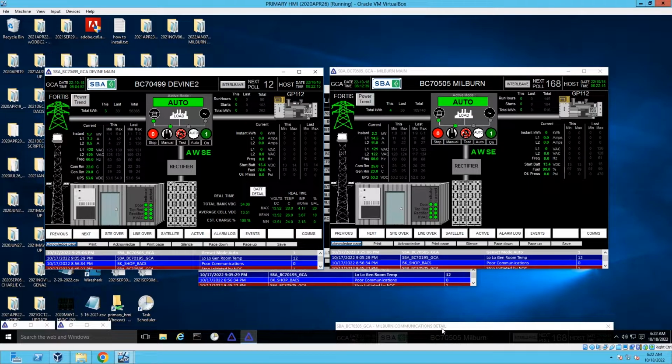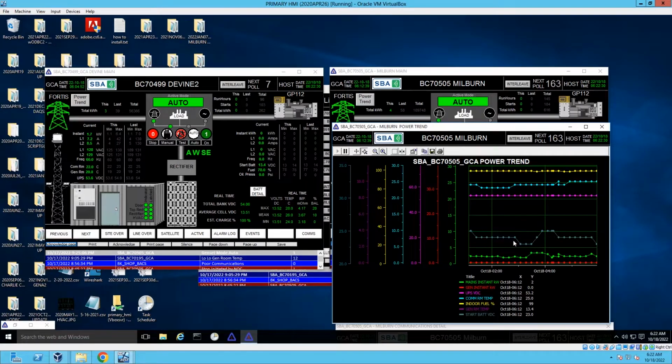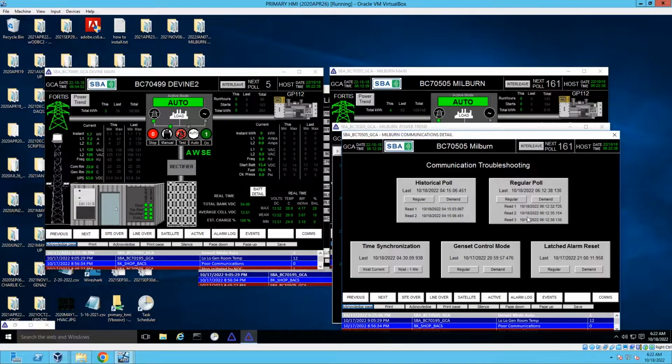Many software packages offer these features, but typically sending data at a timed interval from the host. This leaves operators searching through long-term trending datasets, trying to determine good data from bad data based on flat data or zero values. We have streamlined this into our communications driver, which writes values to ODBC after every poll that successfully reads values from site. The result, only good data, is stored in the underlying SQL tables.